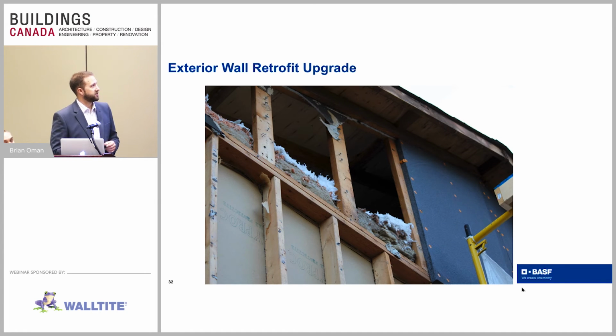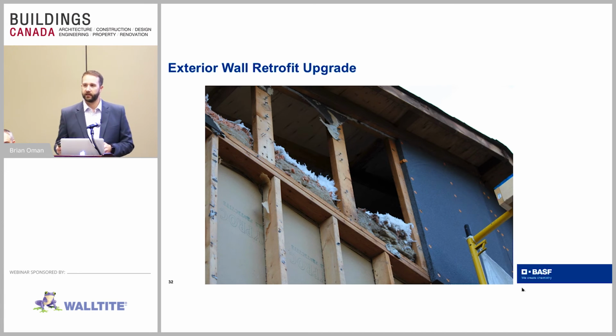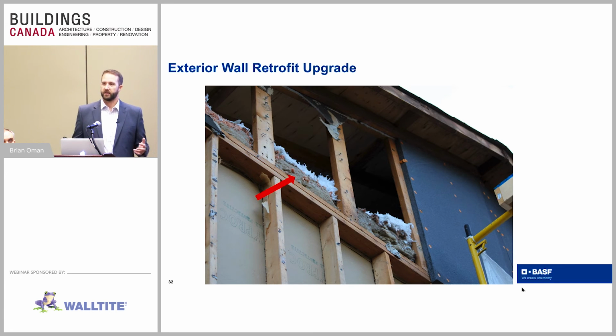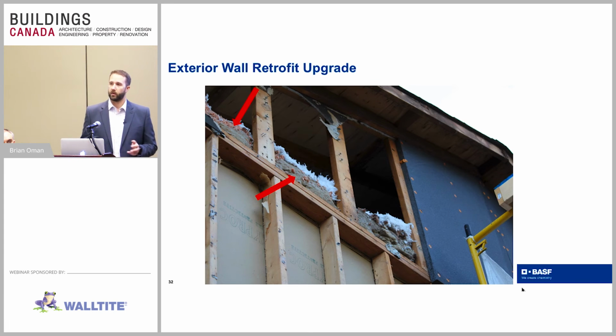And so this is actually the picture that Chris brought up earlier, but I like to call this the attic insulation beam dip because we've got multiple layers of different types of insulation in here. So we've got our original insulation probably installed in the 1960s when the home was built. It's probably a cellulose of some sort. We have some remnants here and there of some pink blown-in fiberglass. We also have maybe some more recent white blown-in fiberglass sitting on top of it.